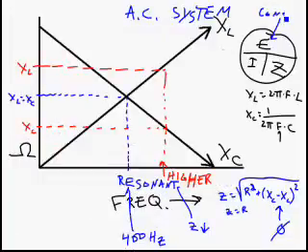Voltage is going to be held relatively constant by the voltage regulator. Remember, the frequency and the voltage and the amp output: the frequency and the voltage are maintained separately. So if voltage is held constant by the voltage regulator by varying the amps, and Z is really low, then I is going to be able to be nice and high.